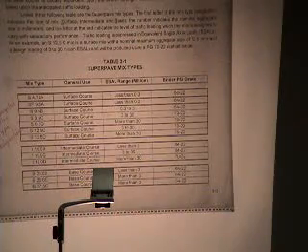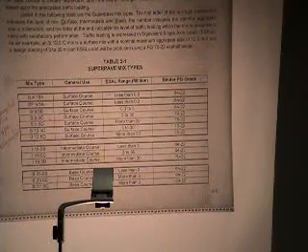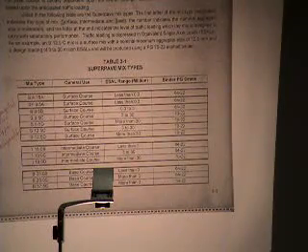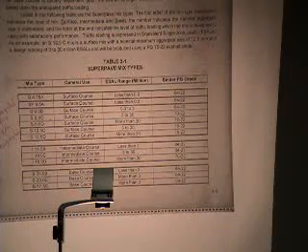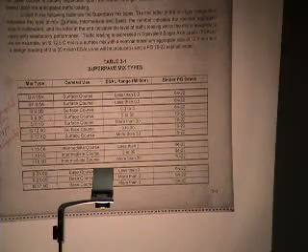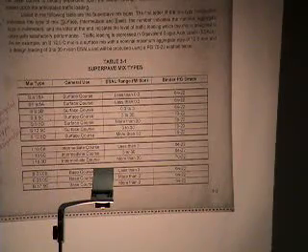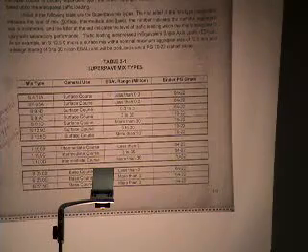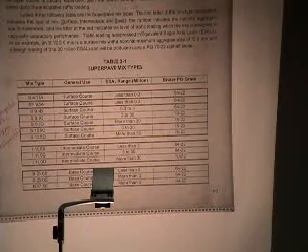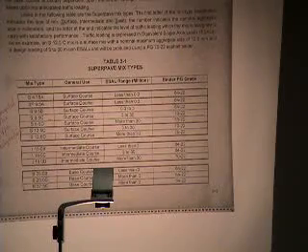As I said earlier, PG64 is the highest it's ever been today. And the indications are it's going to get even higher. But as I say, it's expensive enough as it is. PG70 is a stiffer asphalt. As far as the manufacturing and making of the PG70 versus 64, probably not a lot of difference in cost, but on average it'll run $30 or $40 a ton more. It's primarily for handling, storage, and so on, transport on longer distances because it's just not as readily available.